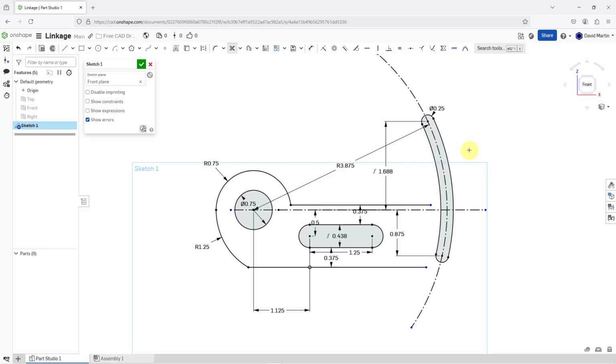And then for the end, I am going to offset the entities for that angled slot, that curved slot over on the side. So I will go to the offset command. Let me pick 1, 2, 3, 4 entities. Let me flip it to the outside, and it needs to be outside a distance of 0.25. Let me left click in order to complete it, and then I'll just hit the enter key to take that distance. And so that is good.